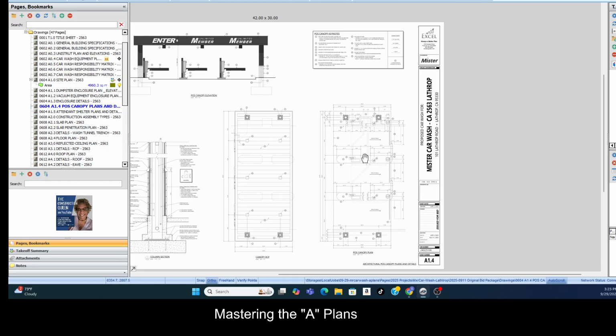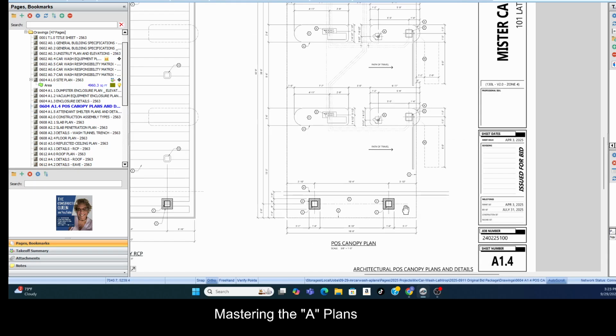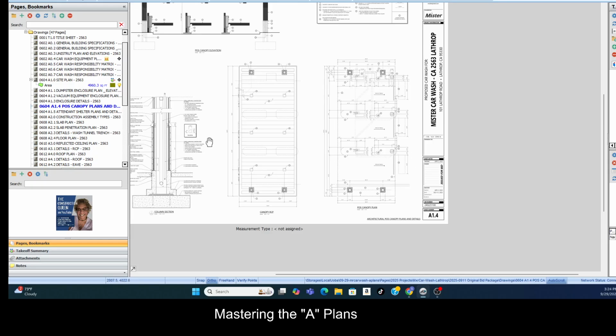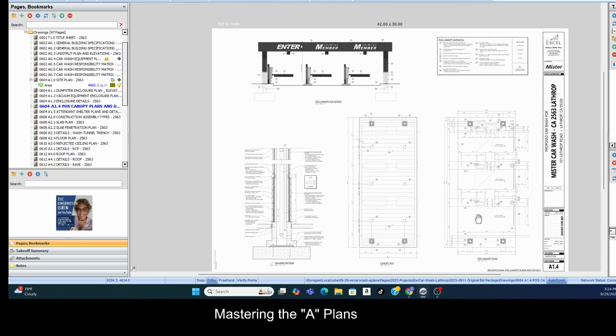Okay. So once we do the takeoff for every part of this set, we're just reviewing the architectural set now, but then we're going to go in and do the takeoff for certain scopes of work. And then you can see in more detail how we break all of this down in terms of measuring, and then breaking it down again in terms of man hours and getting that all together. Because that's really why you have a set of plans, right? So you can look at the set of plans, make measurements, and turn those measurements into dollars.